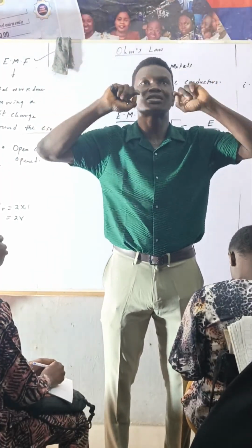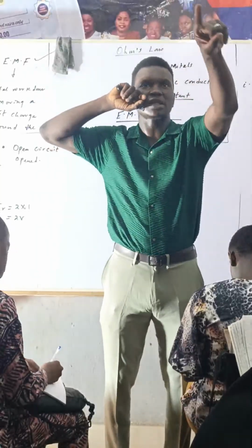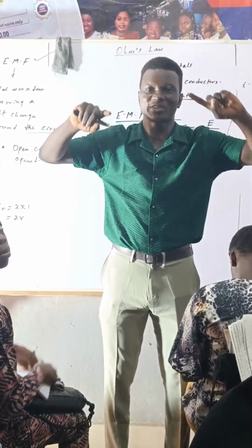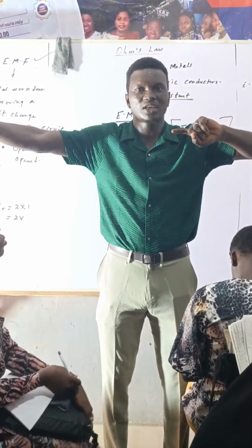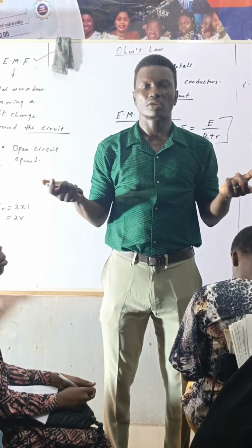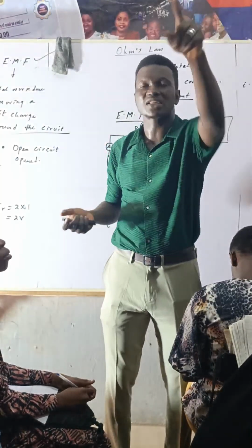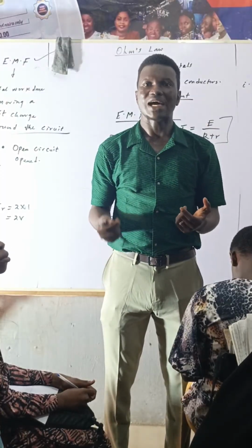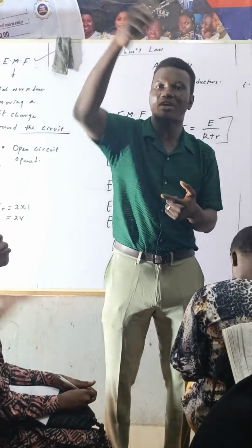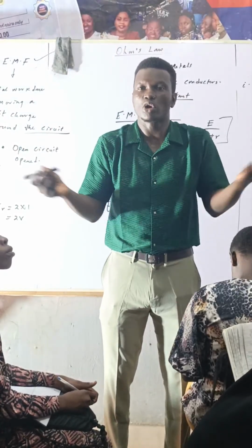So what is this one doing? Except that the person that came to help us connect this made some kind of error. That's why the same switch is controlling both of them. It's an error. If I switch this off, it should not affect that one. If I switch it off and both go off, that means they are connected in series. It should not be.